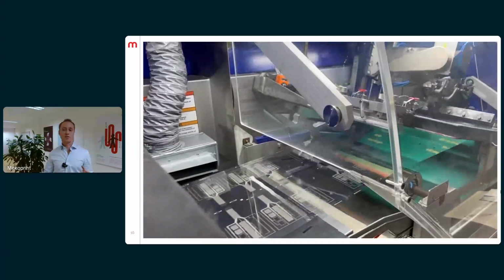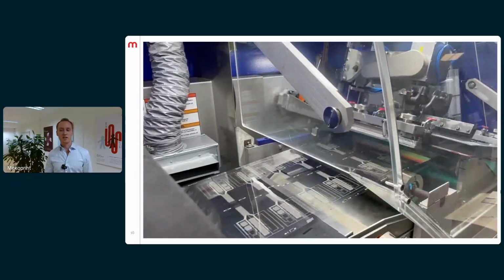And then depending on the required number of layers in the final stack, the roll can run through the machine several times to add dielectrical layers, graphical prints, and so on. And that's how the final sensor is built up. So after printing, we also have roll-to-roll conversion options for lamination of adhesive, die cutting into specific shapes. And we also do have automated optical and electrical testing available in-house to make sure that we deliver functional sensors that meet your requirements.